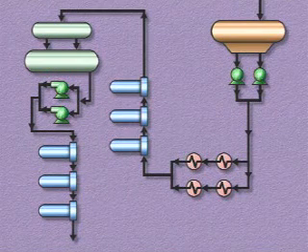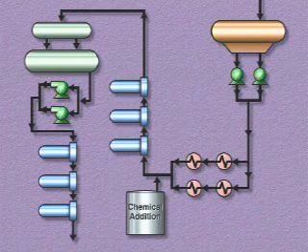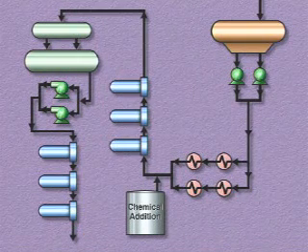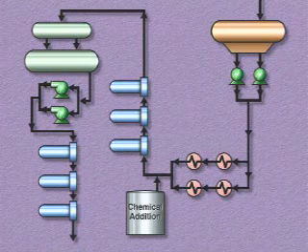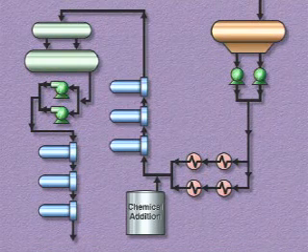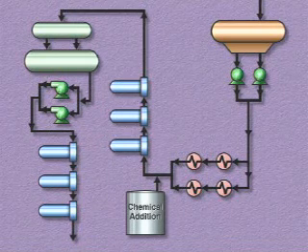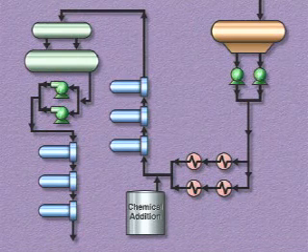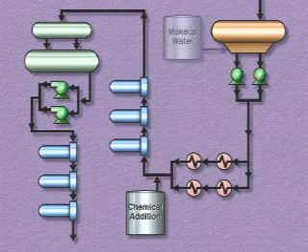Additional systems are often connected to the basic condensate system that we've just seen. Typically, a chemical addition system is connected to the condensate system. In some cases, however, a chemical addition system may be connected to both the condensate side and the feedwater side of the system, or just to the feedwater side. In any case, the chemical addition system has equipment for adding chemicals that minimize corrosion and control the pH of the condensate or water. pH is a measure of how acid or alkaline the water is.